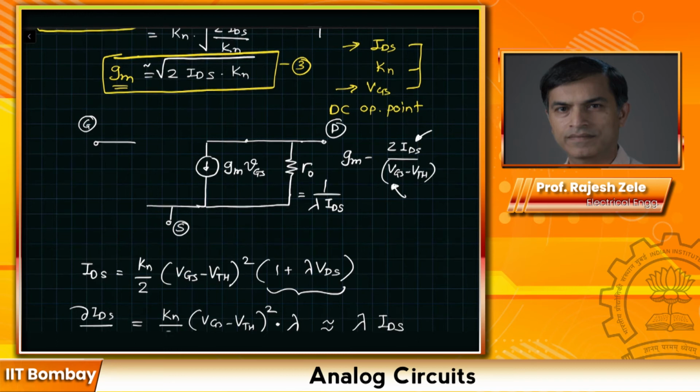So far we have discussed so many different things about the MOSFET, but all these things we have talked about are in equation form. You really need to have a feel for numbers. So I'm going to give you the model numbers that you will find in a SPICE model card for a 0.5 micron CMOS technology. And again, this is an example. These numbers do not represent a particular foundry, because all these numbers from each foundry are confidential. So I'm using average values to give you a perspective about what these numbers mean and how you calculate the different coefficients that you need for hand calculation.